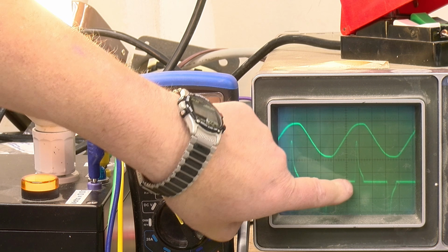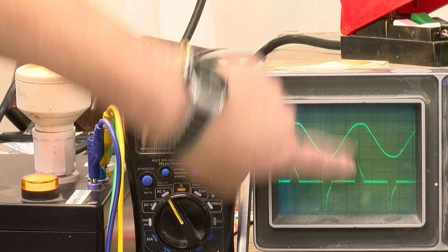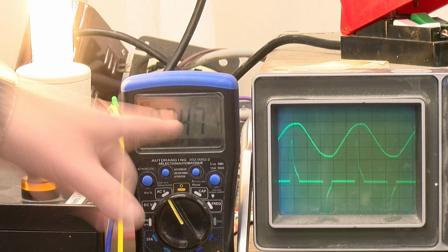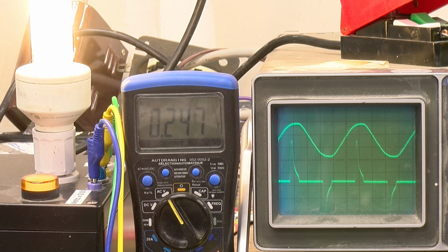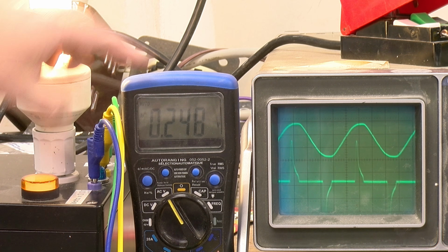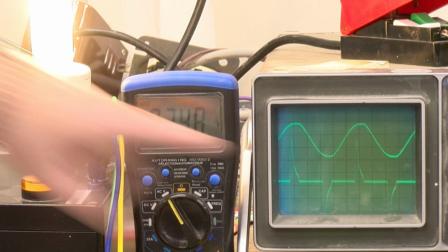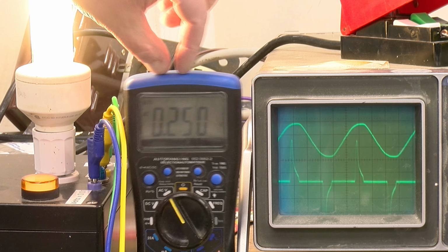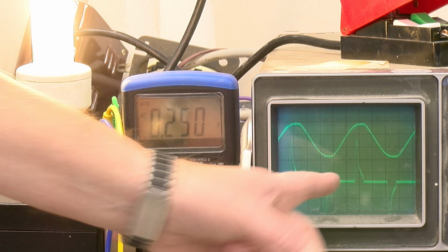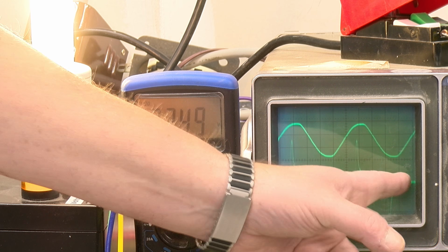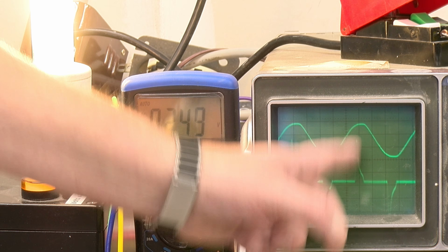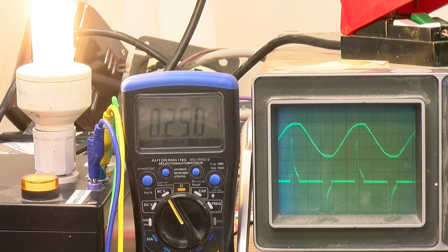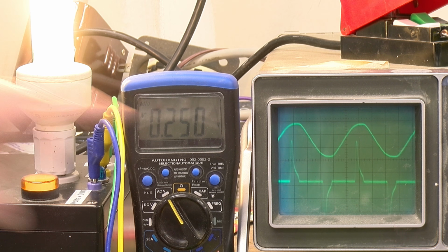How's that? So all the current is being drawn in these spikes over here. We're seeing an average current of about 1/4 of an amp, according to the voltmeter. I'm not sure how much I trust this because these spikes are so narrow. The accuracy of the voltmeter will depend on how many times it samples the voltage along here, and you could certainly see it not getting the spike properly, or only sampling at a few positions to get an average type current. So I'm not 100% sure.